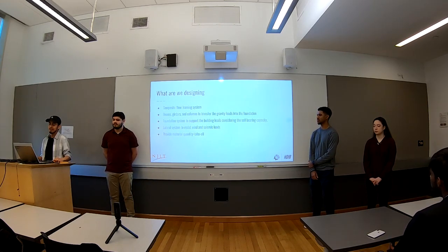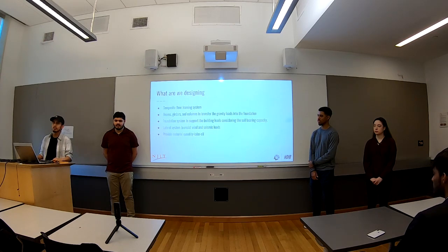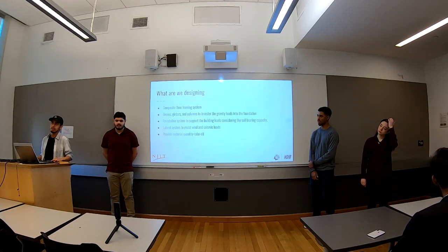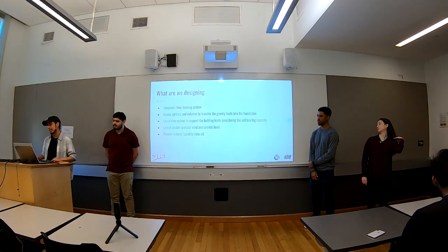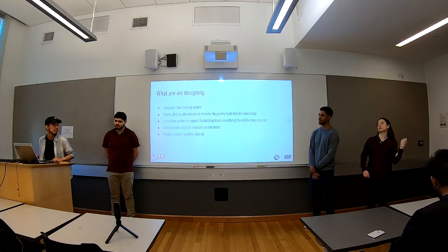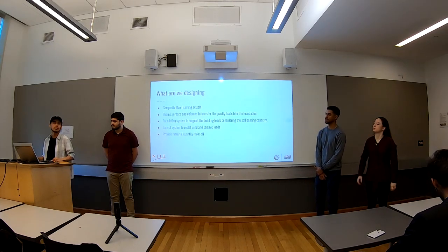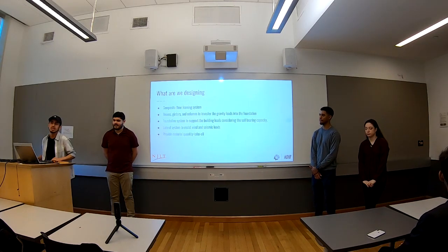And we also have to design a lateral system to resist lateral loads in our design because we are in a high wind area, not so much earthquake, but we also have to consider wind since our structure is going to be really tall. We have to also consider wind and seismic loads. And at the end of our project, once we're all done, we're going to provide an estimated material quantity takeoff in terms of how much material we're using and how much it costs overall.